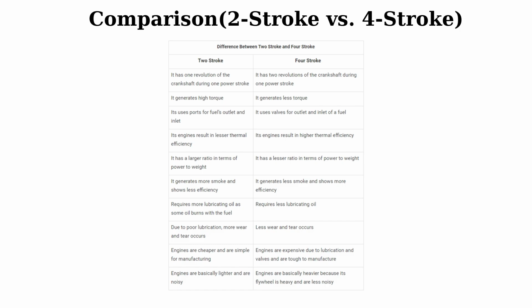Okay, now the important point, environmental impact. Two-stroke engines produce more pollution. This is because combustion is less controlled in the two-stroke, and some fuel isn't burned completely. It can escape from ports during the process.